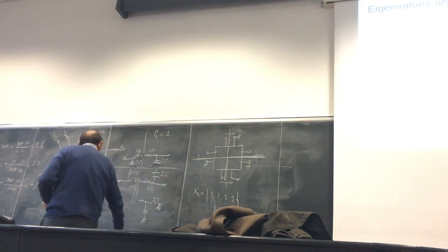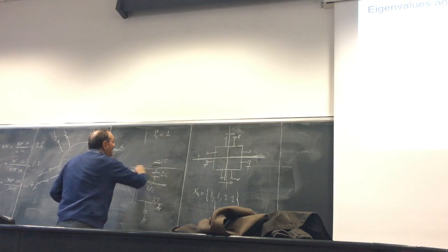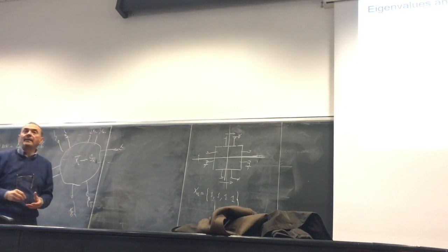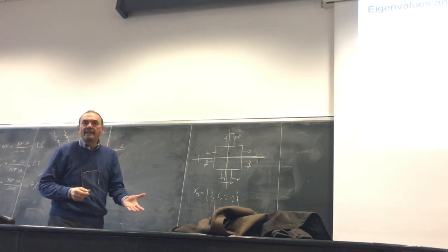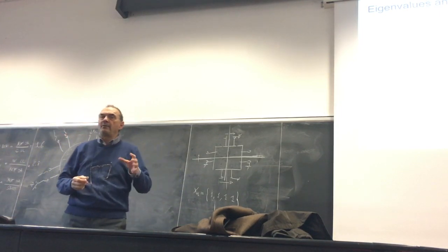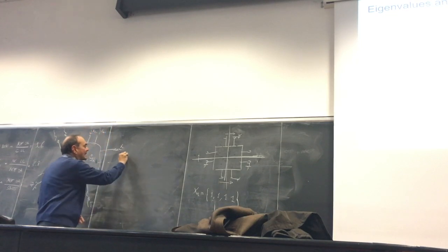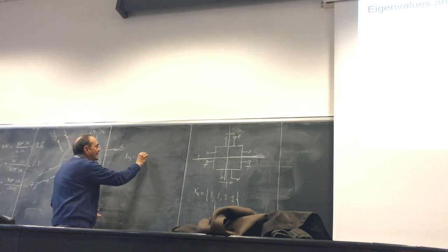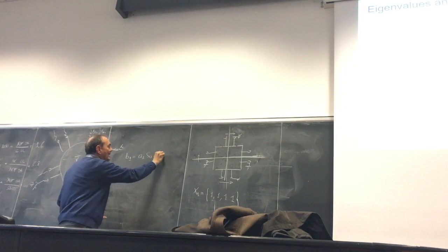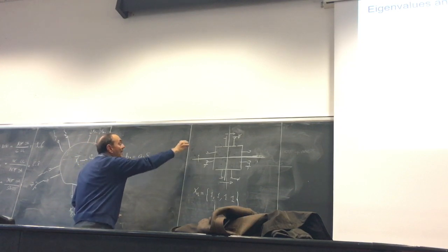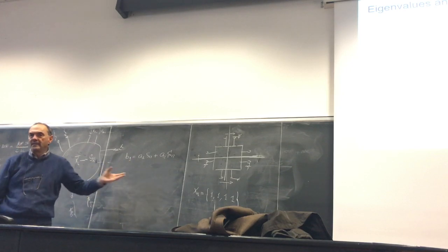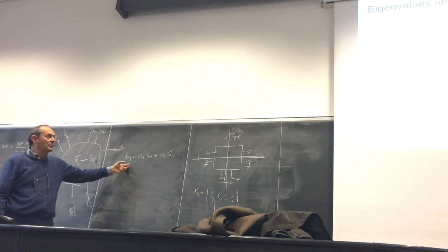But also in this case, the answer is relatively easy, because what we have to do is to remember the definition of the scattering matrix or the impedance matrix or whatever you are considering. In the case of the scattering matrix, you know that the reflection coefficient at port 1, for instance, is A1 times S11 plus A2 S12 plus and so on. Okay? Let's consider the case of a two-port, which is very immediate and easy to report.